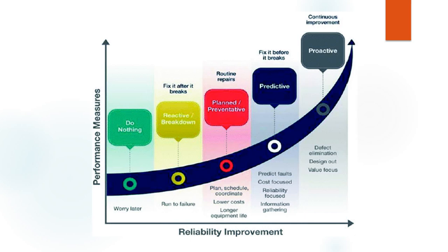What if you have 4 turbines and you need exactly 3 in service and the fourth one is redundant? Is it critical or not? And how much criticality? It's different, right? Then there are many factors we consider in that criticality. And according to this criticality, you decide exactly what type of maintenance philosophy you need to apply to this equipment in order to run it in a reliable way.